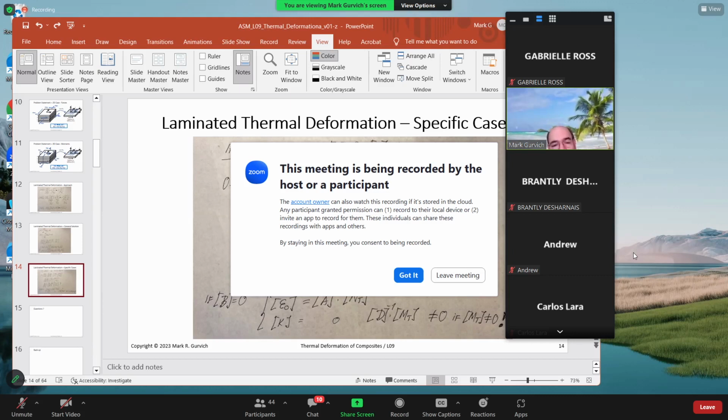The inverse multiplied by the original gives you unity, so you can ignore it. So now you have just epsilon sub-zero and curvature, and you have the inverse or compliance matrix of the laminated package, ABD minus 1, multiplied by NT and MT.